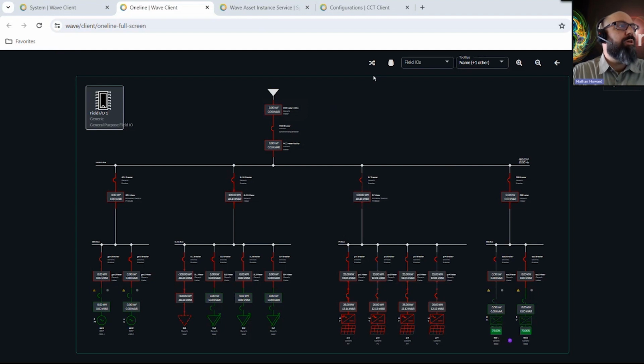So we've set up some internal ramps that are configurable for the assets. We want to make sure we're not adding large loads or taking sizable production offline suddenly. So we'll have these timers or ramps between when we're adding assets to the system.